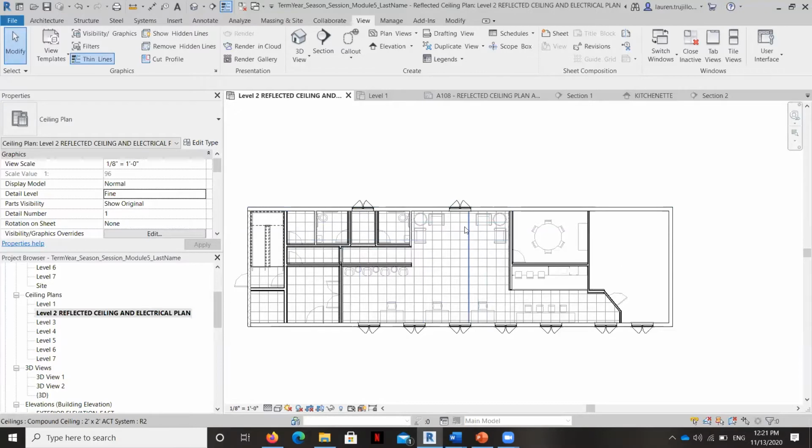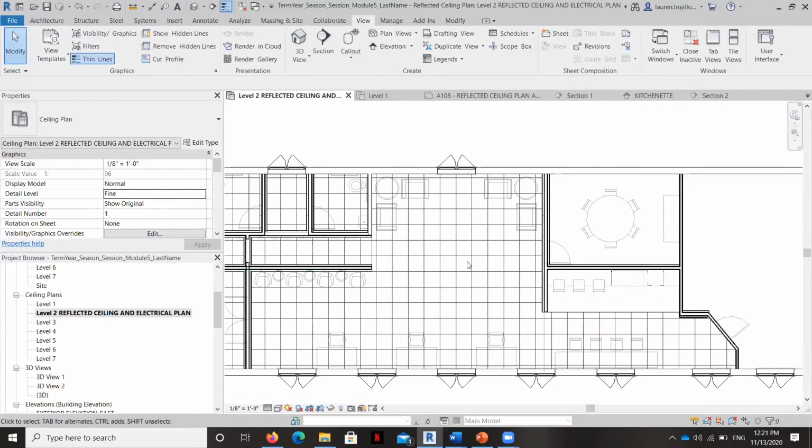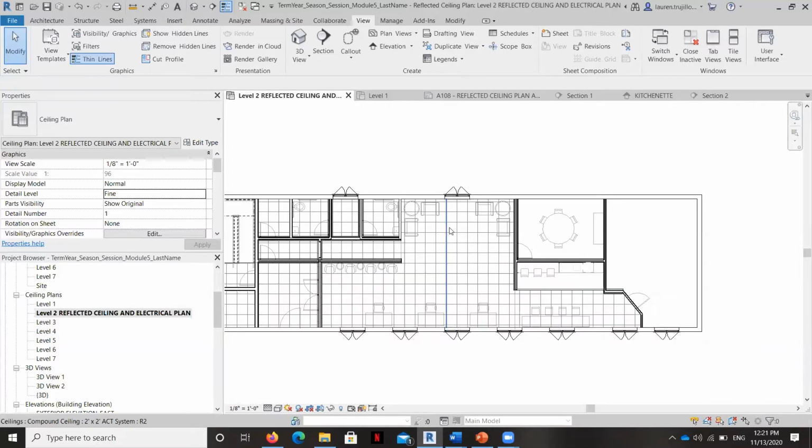Keep in mind that we have this grid laid out already that is going to allow us to organize elements in a repetitive way. But if you don't have a grid like this in the ceiling, then you would have to establish one by creating grid lines. And that's really important because a reflected ceiling plan needs to be aligned. Elements on it need to be aligned. Things need to be placed exactly, within these ceiling tile elements and not crooked and things like that. So we're fortunate here, but we also know how to draw grid lines if we need to.